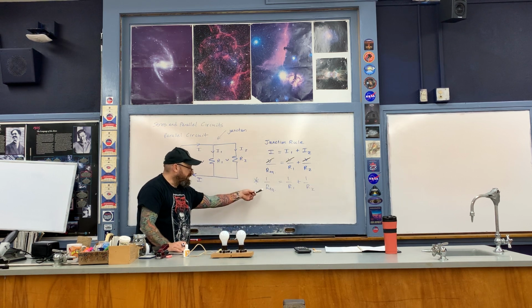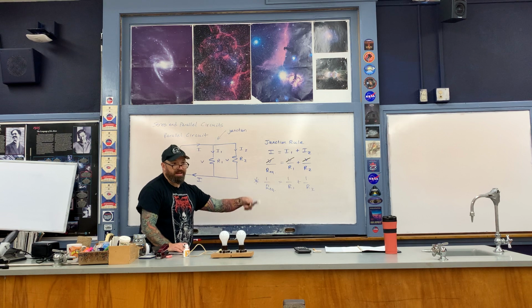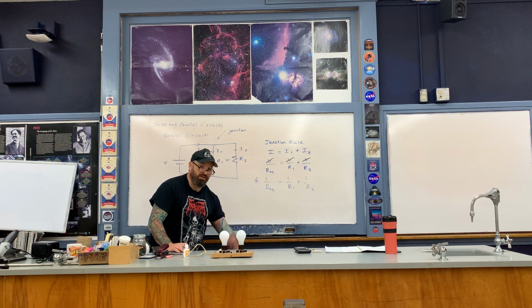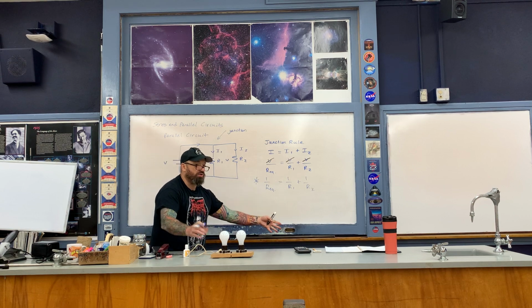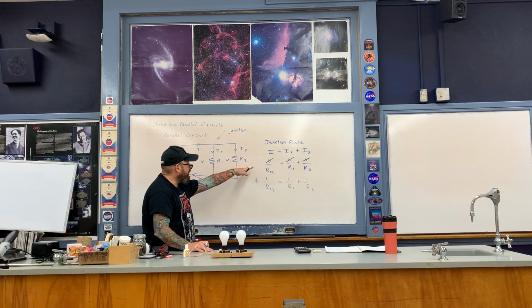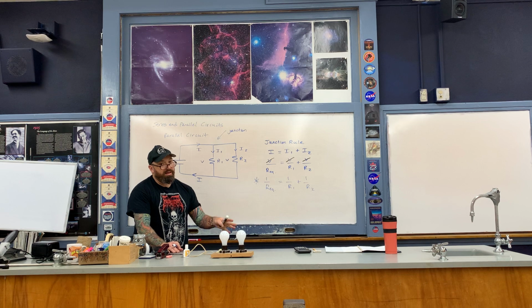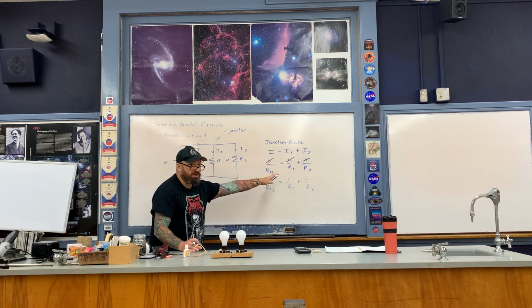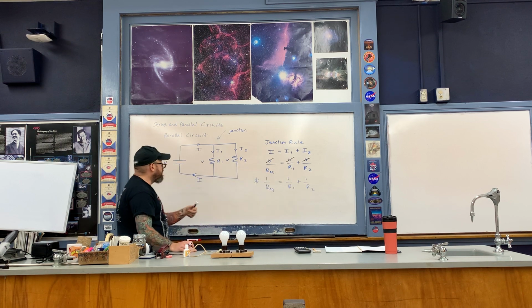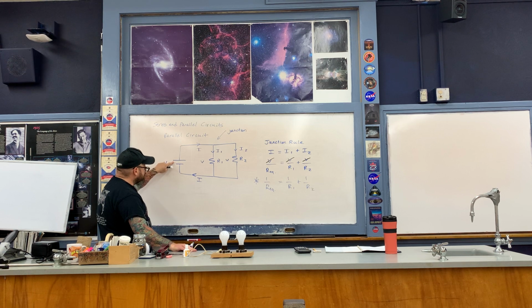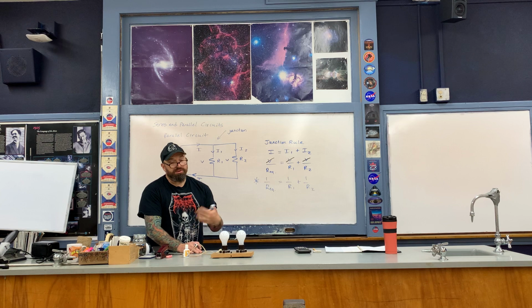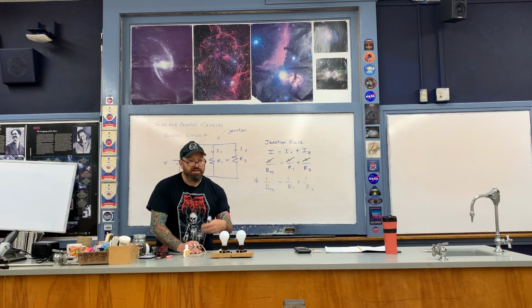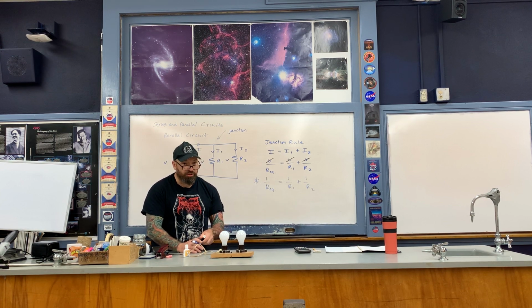Overall, the equivalent resistance, R equivalent, is less than the sum of R1 and R2. And the reason for that is because you basically are widening the stream by adding more and more branches to the circuit. When you add more and more branches to the circuit, you make it easier for the current to flow. So therefore, for a particular potential difference V, the amount of conventional current increases. You'll see this in one of my mathematical examples a little bit later on in the lecture.